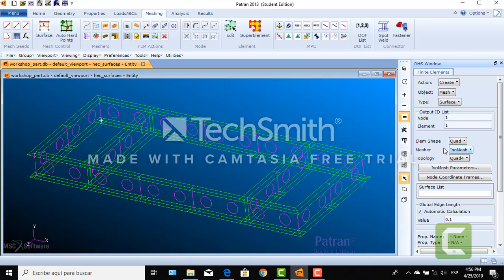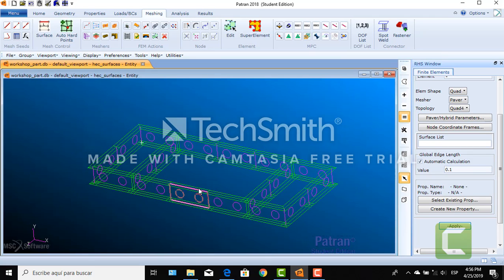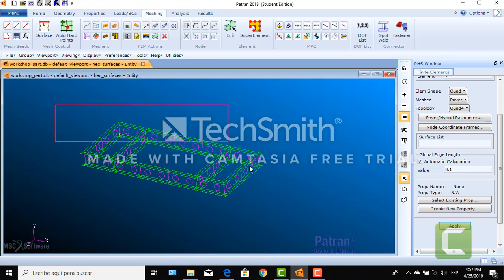We leave the element shape as a quad, and the mesher we change it to a paver. And the topology, we're just going to leave it at quad 4. And the surface list, in this case, we're going to be selecting the whole entire thing. So I'll just go back and we go like this. There it is. Just selected everything.